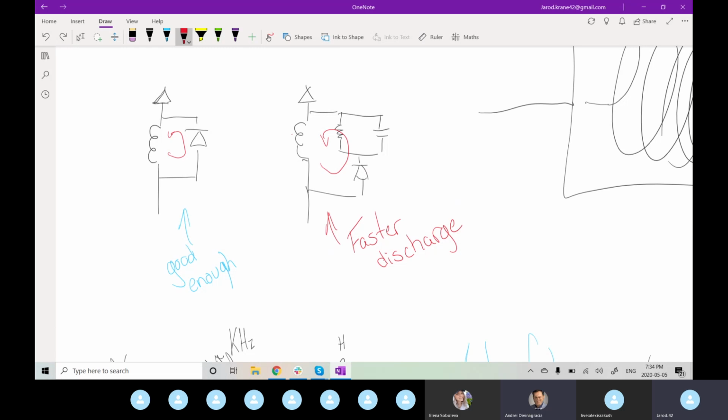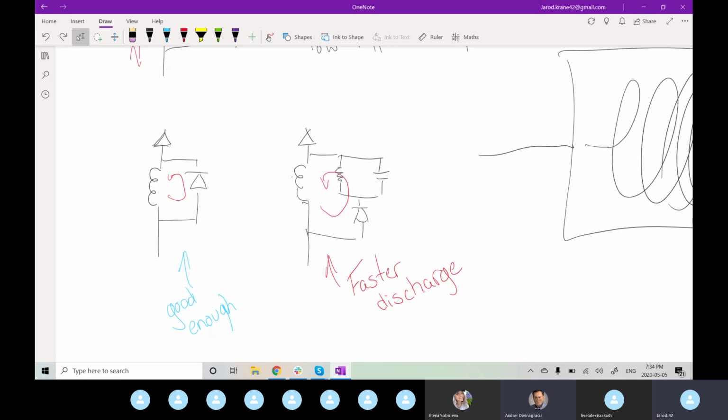So you'd see this in PWM circuits then, this type of snubber. Even at that, like I said, in a quick simulation test that you did, it was 20 millisecond settle time versus 4 millisecond settle time. So it's not super critical, but once you start getting to higher frequency, it really starts to show.